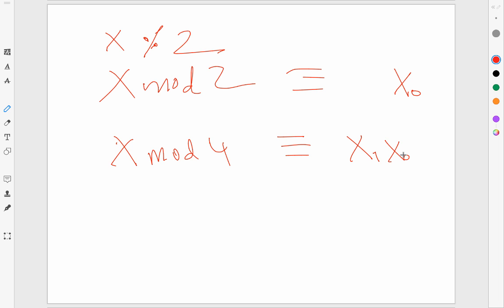Data input has nothing to do with the clock signal. So while we do talk about flip-flops updating themselves when they see a transition in the clock line, you should not think in terms of feeding the data line into the clock input of the flip-flop.